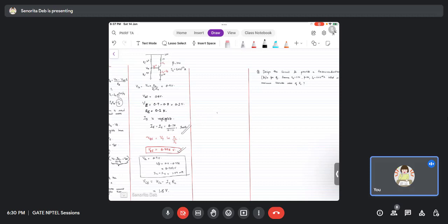So you would be seeing that the main purpose is to make base current negligible. Now I cannot make base current negligible just by saying it, I have to make the circuit in such a way. So in the first method we had seen that if we make a choice of R1 and R2 properly, it will make sure that the base current is negligible. But because of the temperature variation, because of the heating of the resistor, the value of R1 or R2 may change. Once the value of R1 and R2 changes, the assumption of base current negligible may not be fulfilled. Therefore, that circuit is not reliable, right?